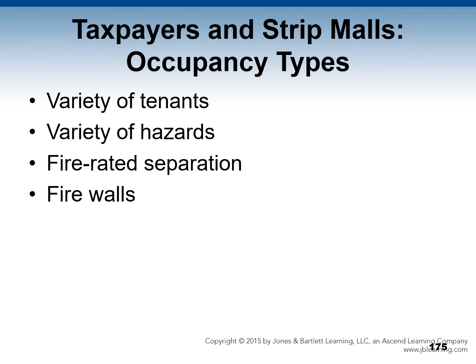Most building codes require a fire-rated separation between different occupancy types. However, no rated separation is required between a group of strip mall tenants if all are the same occupancy type. When a building area becomes too large, firewalls are often required to break the structure into smaller fire areas. Make sure that you review and are aware of local building codes.